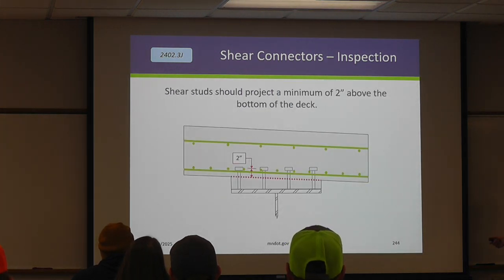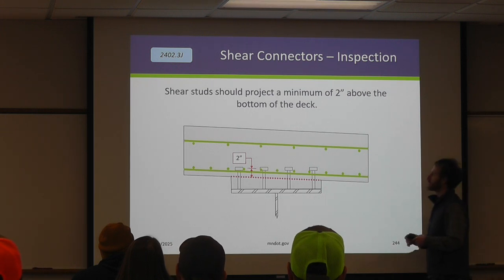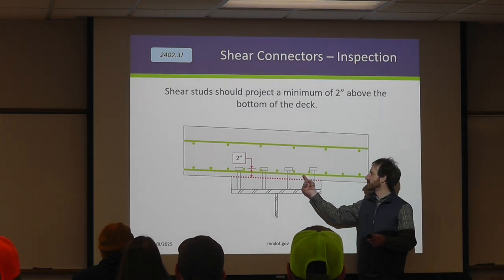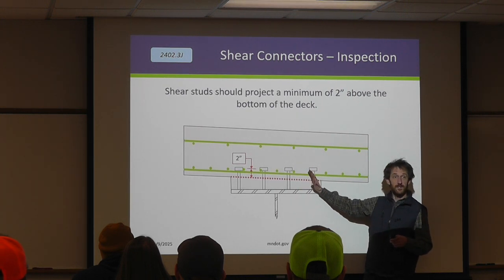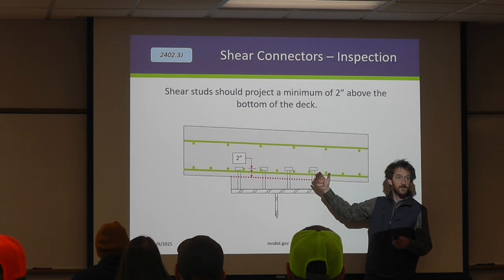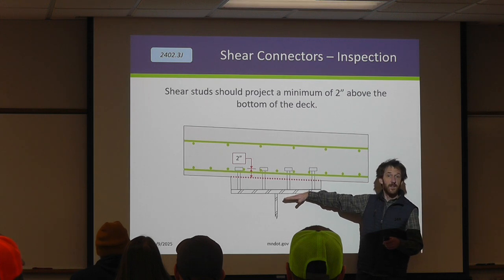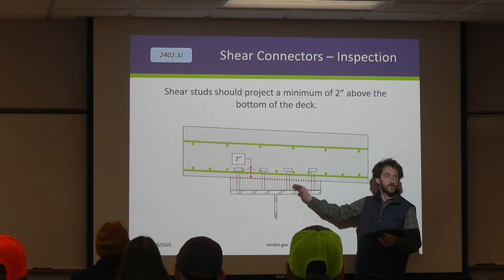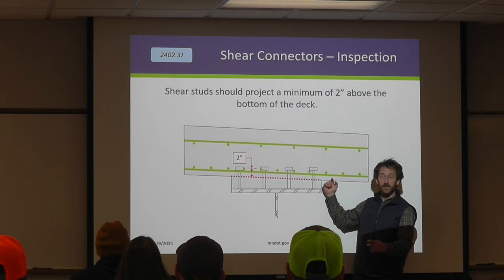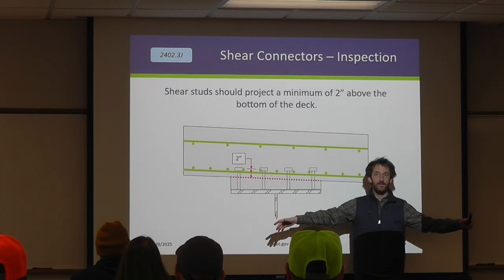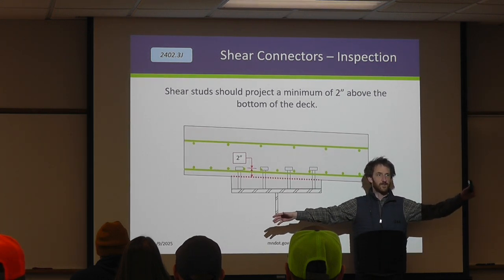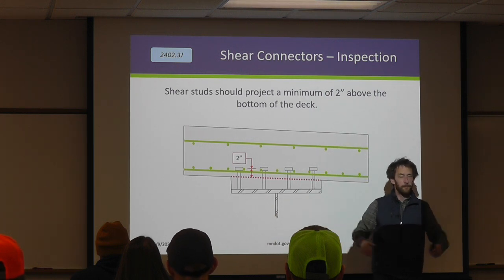So what does that look like? Think about a plan view. You've got your bottom mat of steel, and your heads are projected up in there. This can become an issue with really steep cross slopes, like if you have a 6% cross slope through here. The flange is still flat. We don't build the flange at the cross slope, so your stool height varies from one side or the other. I've been on a project where this flange is 48 inches wide. If you think about that over 6%, your stool heights can vary quite a bit.